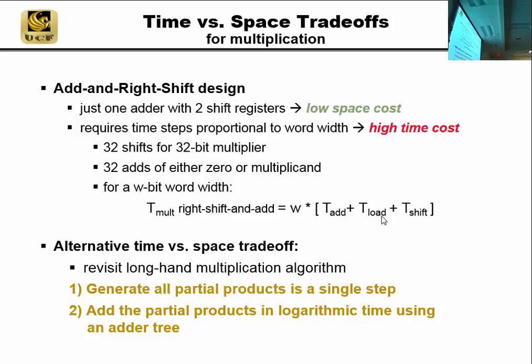And what do we do when we do filters? Time constants, right? And you put a capacitor and inductor and you make a tank, right? And the signal comes in and you try to filter out this. You make a notch filter, you make a bandpass filter, right? If you haven't seen it, you'll see it soon. That's analog signal processing. What's the problem with that? It's not very programmable. The great thing about digital signal processing is we say, you know what, that's too hard. That's great for physics and drawing squiggles on the board, but the real way we do everything these days is what do we do? Convert to binary right off the bat.